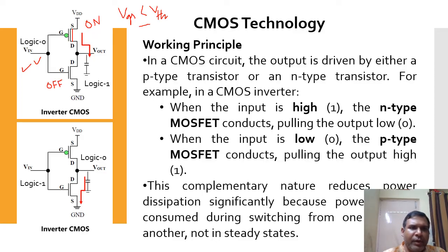This N-type MOSFET will not create any inversion layer between the drain and source terminals, because this is the negative voltage, and on the reverse side, what will happen? Positive charges, or holes, will be attracted towards the oxide layer. But to create an inversion layer, because in an N-type MOSFET the source terminal and the drain terminal are connected with the n diffusion region.